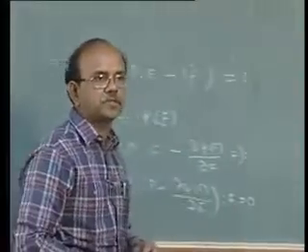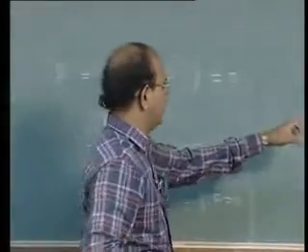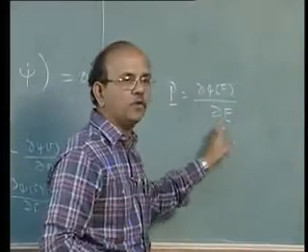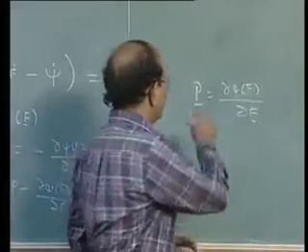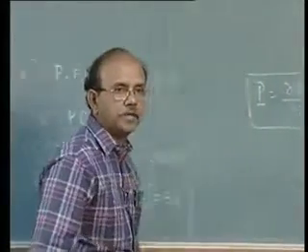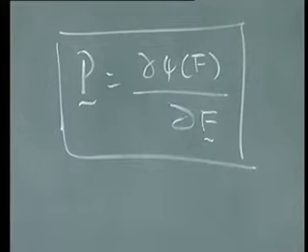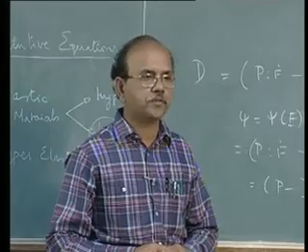First PK stress is the gradient of, or is the ∂/∂F of the strain energy. So that's a very important, probably the most important step in the whole development of constitutive equations.